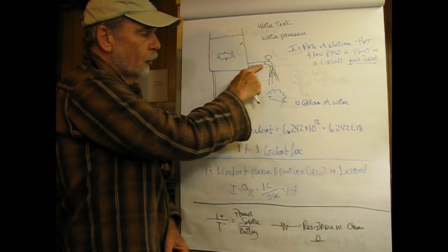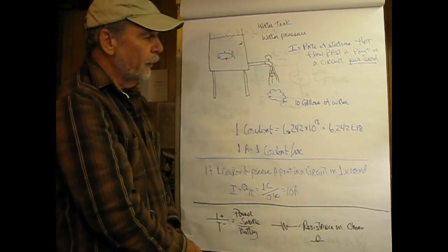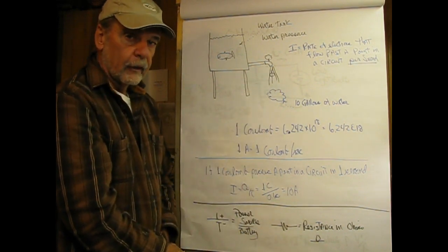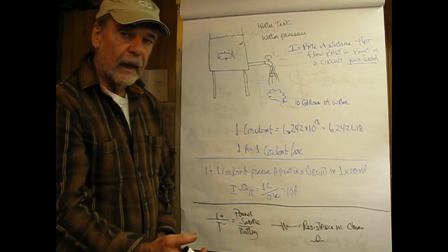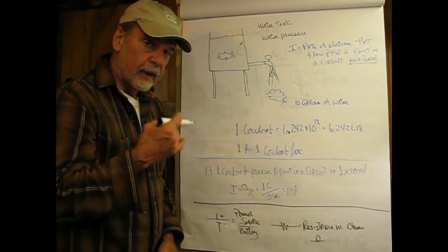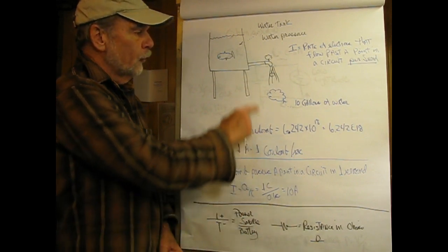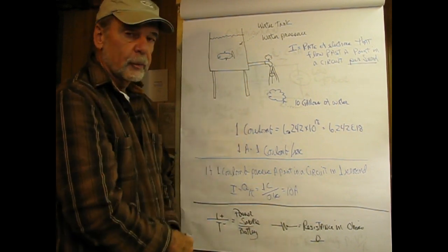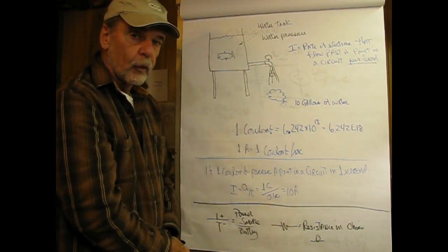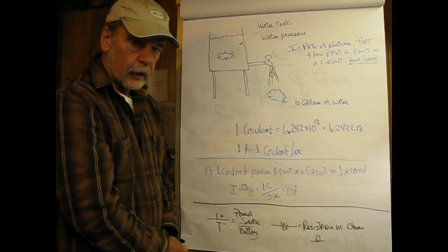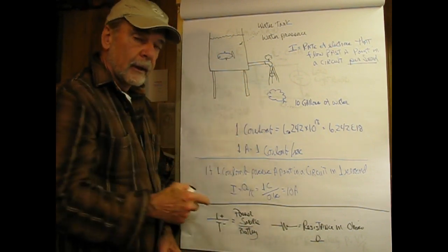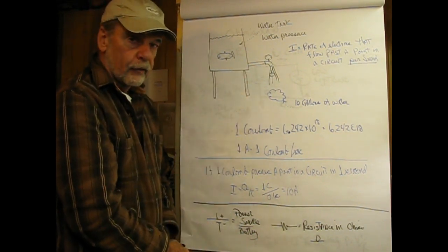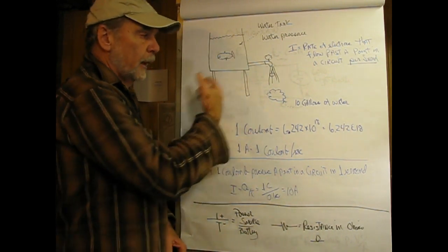Now the pipe also offers resistance to current flow, so if I open the spigot 100%, I would get a flow of water coming out of this in gallons per minute, gallons per hour. What's important is that it's a rate of flow. Also note that if I had a larger pipe, suppose this was 1/2 inch and I replaced it with a 1-inch pipe, and the spigot would be adapted to 1 inch, the flow rate would be much larger. And that is because a larger pipe, and think of cross-sectional area in this case, is larger than that of a 1/2 inch pipe, hence the resistance to the flow of water is less and more water flows.